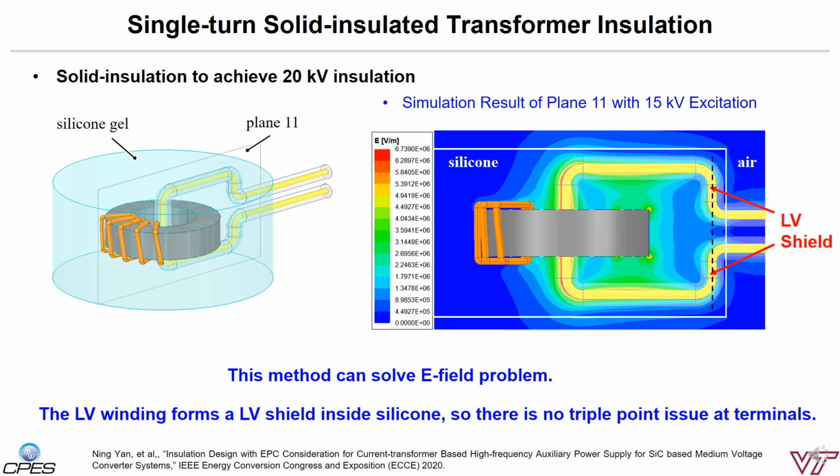By doing so, we successfully push the peak E field from the winding slot exit location into the epoxy. Therefore, no high E field will show in the air. This design allows us to avoid using any special termination structure while achieving a high voltage PD-free insulation.